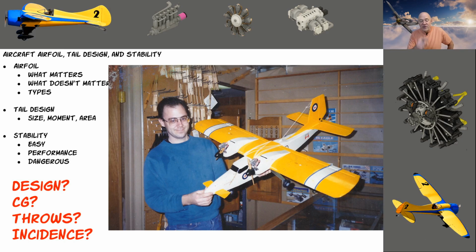But putting that stupid canard on the front of it, every time the nose had a positive incidence, that canard caught the air and tried to pull the nose up. Then I would push it down, and once I had a negative, it would pitch it down. So the entire time I was test flying this plane, it had a porpoise to it. It just porpoised up and down. And once I broke those off, it flew perfect. So be careful you don't add things to your airplane for a cool factor that makes it fly like garbage, because that's what you don't want to do.